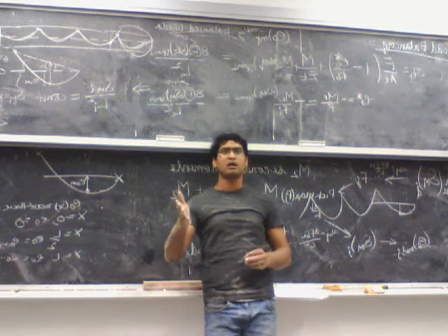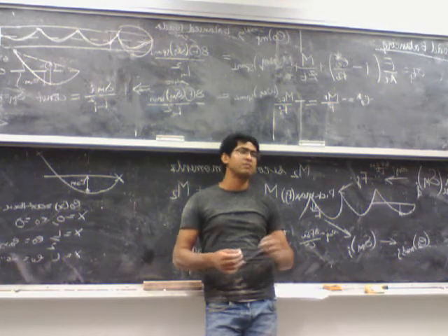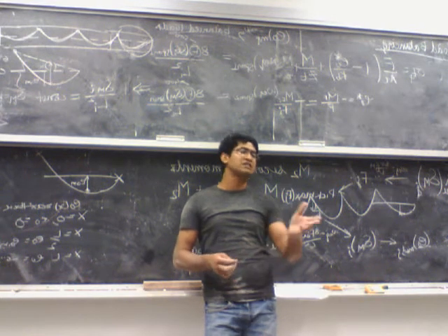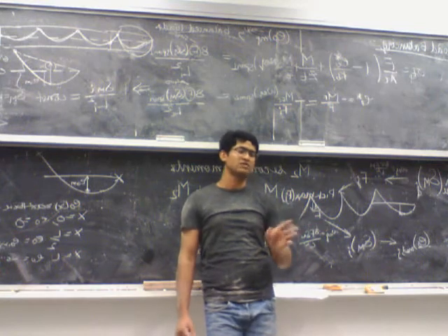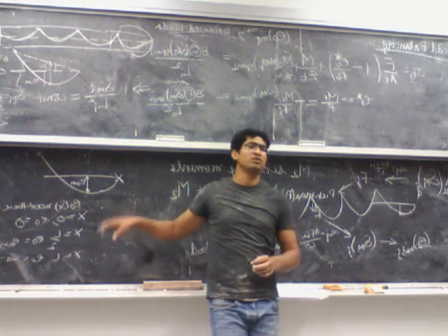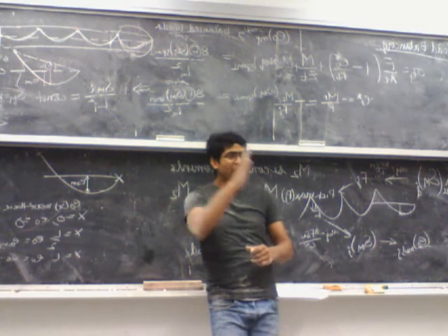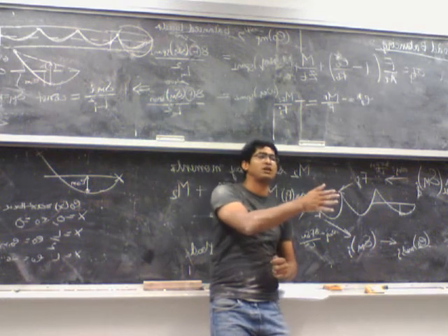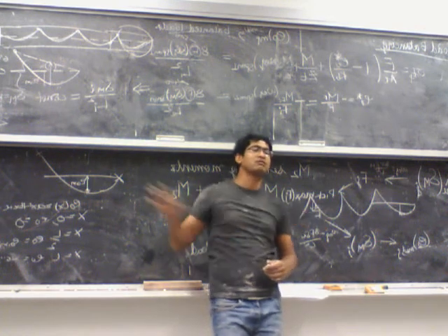So if you are short on time, you can always start with 85%. In the worst case scenario, even if it doesn't check out, it's not a big deal, because this whole thing is time consuming. You find out the tendon profile, you differentiate it, you find out the location of the maximum, you plug the values in, then you get the maximum value.